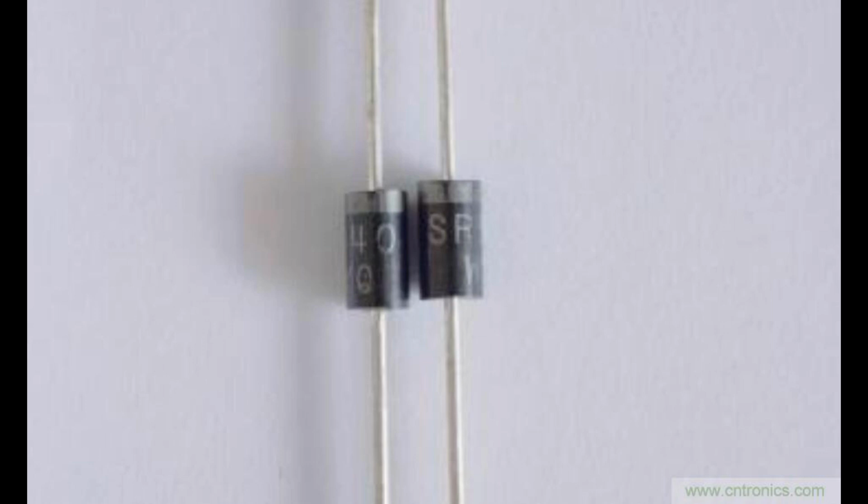Fast switching devices are used in data communication systems such as fiber optic transceivers to transmit and receive data at high speeds. Fast switching speed is achieved through various techniques and advancements in semiconductor technology, such as smaller gate capacitance. Reducing the size of the gate capacitance in transistors allows for faster charging and discharging of the gate, resulting in faster switching.